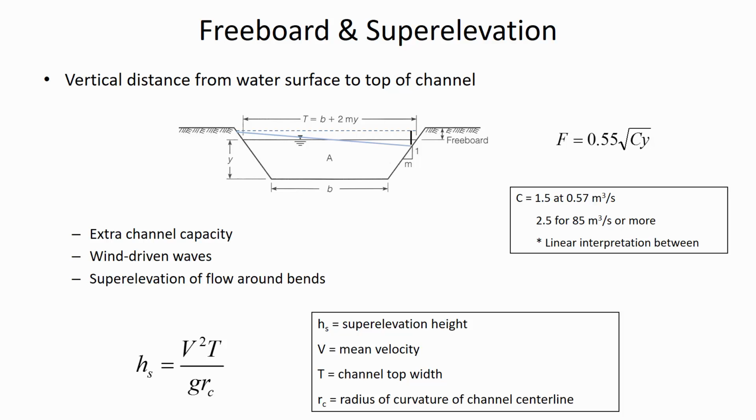But what you need to check at the end is making sure that the freeboard that you've established, that extra height above where the water surface is expected to be, you need to make sure that at least the freeboard is greater than the expected superelevation height.